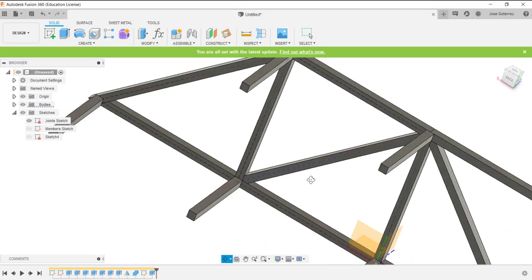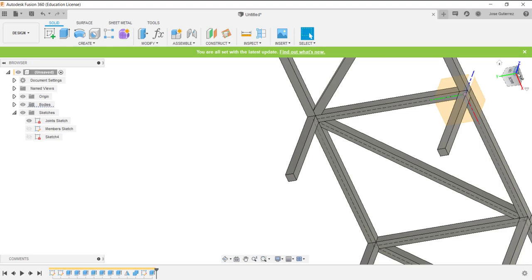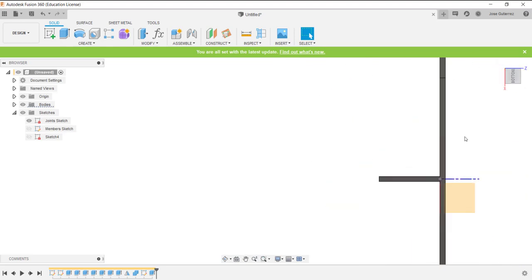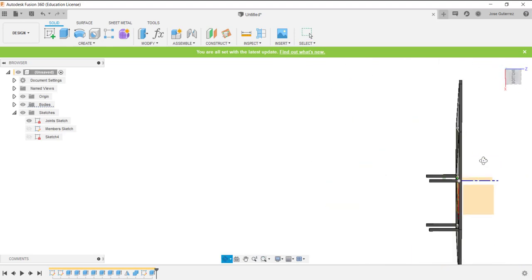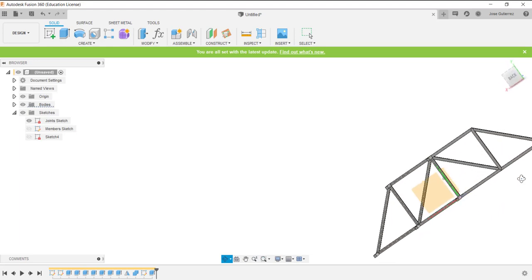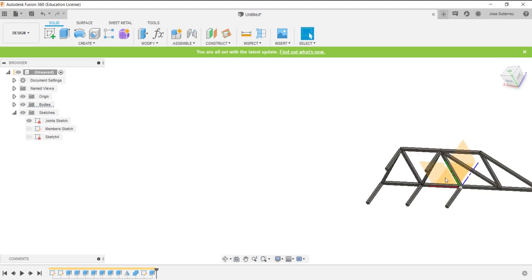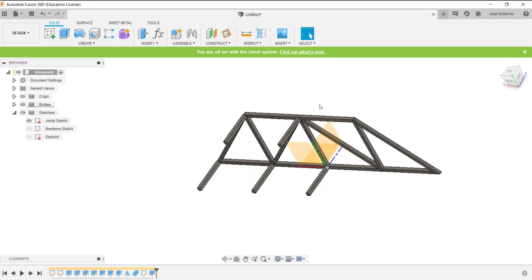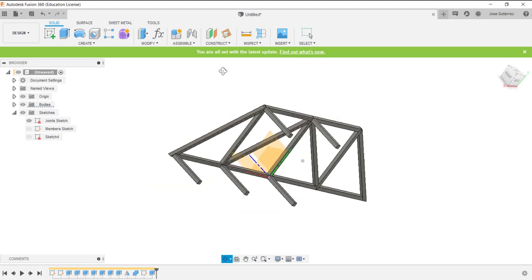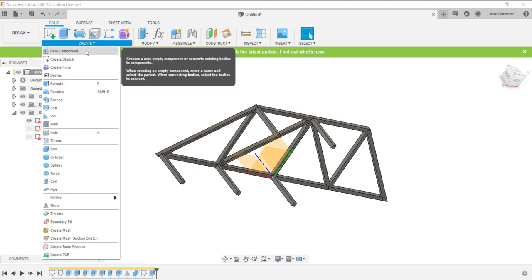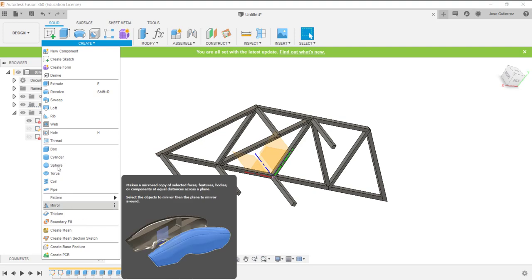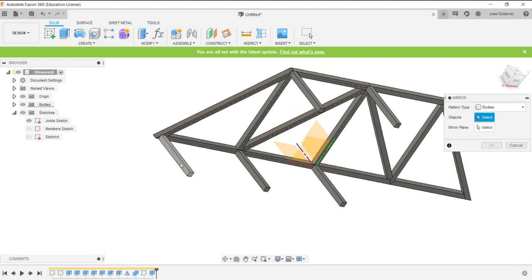So now we've got a nice sketch. Let's take a look at the bottom, or solid model of our cross members, but it's only for half of the frame. So we're going to use that mirror operation that we did before. Go under Create, Mirror, and let's select the members that are not along the middle axis, because we don't want to double create these.